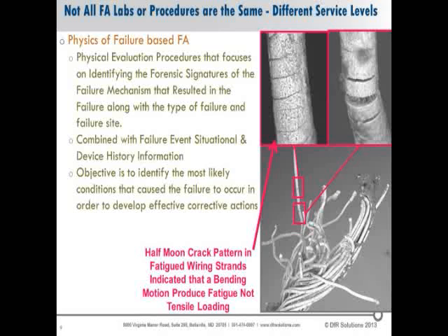When I was brought in, I looked at this curl around, and I looked at each wire strand individually with a simple magnifying glass, and I saw this half-moon cut across only half of the cylindrical wire strands. That told me the wire was being bent, not pulled. If it was being pulled, it would have formed an hourglass, narrowing down around the entire circumference of the wire strand, not a sharp cut around half of it like that.